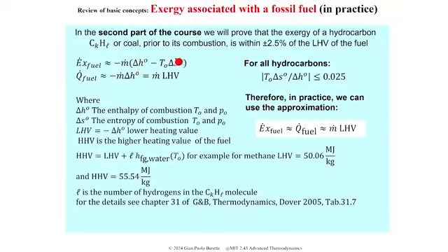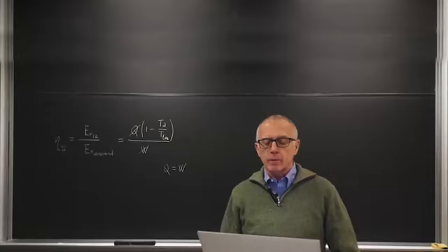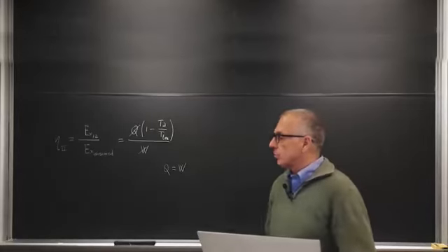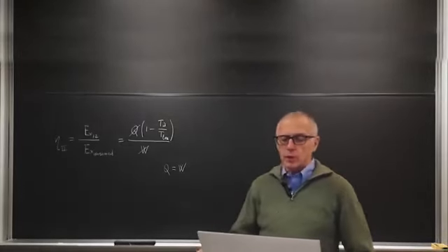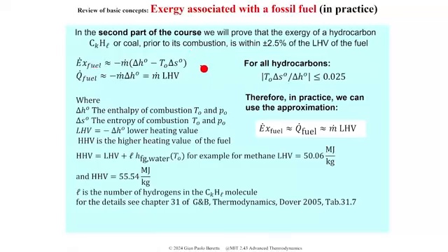So this combination is the Gibbs free energy of the combustion at standard conditions of pressure and temperature. That's the meaning of the superscript up there. And with a minus in front, that will be the most important contribution to the exergy of the fuel. There will be some term related to mixing that we will see later.